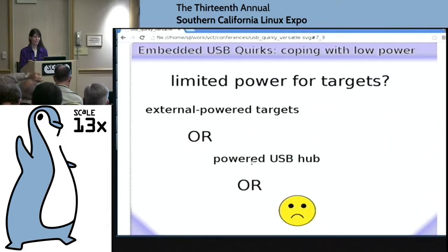And if neither of those apply... So, a question: does the host controller have a power controller or a power regulator in it, or is it just power passed through the connector? It comes from the embedded board. It'll usually be a regulator that's shared by other stuff on the board.